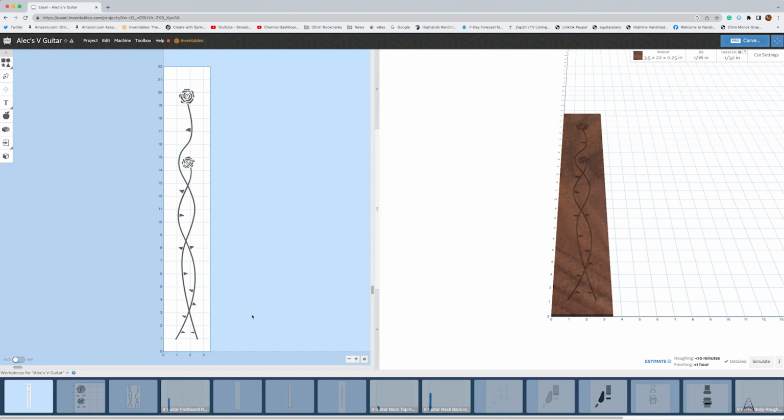But for this particular project, the first thing I'm going to do is make the fretboard, and that's going to involve cutting the inlay pocket for my fretboard design. That's the first operation I'm going to do. When I cut this file, I'm just cutting a straight two-dimensional pocket into the fretboard blank so I can import an SVG file of this design.